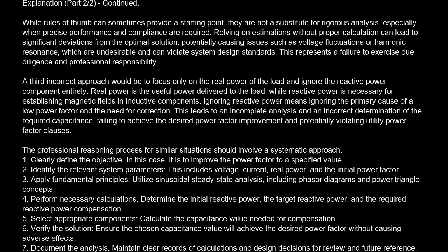A third incorrect approach would be to focus only on the real power of the load and ignore the reactive power component entirely. Real power is the useful power delivered to the load, while reactive power is necessary for establishing magnetic fields in inductive components. Ignoring reactive power means ignoring the primary cause of a low power factor and the need for correction. This leads to an incomplete analysis and an incorrect determination of the required capacitance, failing to achieve the desired power factor improvement and potentially violating utility power factor clauses.